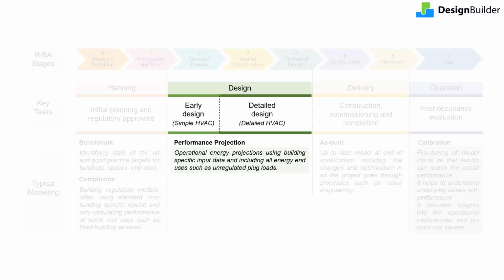areas where detailed HVAC modeling is particularly beneficial include a greater ability to optimize air side modeling of mechanical ventilation systems and water side modeling of heating and cooling systems, including heat recovery. HVAC modeling is also powerful for simulating heating and cooling plant, fan, and pumps performances in more detail, plus the testing of control options.